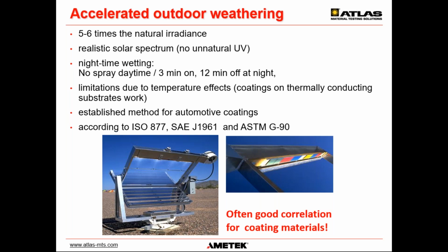It's a very realistic solar spectrum, the actual solar spectrum, and it has the ability for nighttime wetting cycles or no spray cycles throughout the day. Some of the limitations are that you also reflect infrared energy, so some of the materials may get too hot using the traditional exposures.